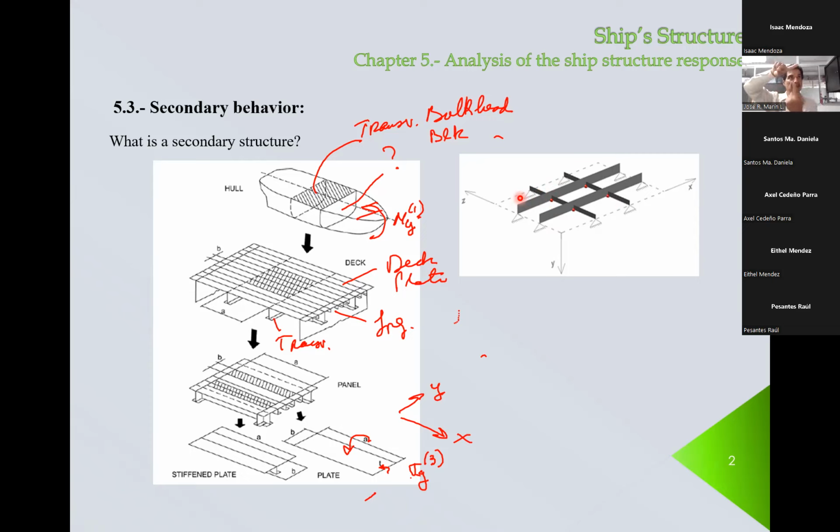So on the stiffener, the force will be upward. And the same force will be acting on the girder, but in the opposite direction. So that's a common quantity. And another common quantity is the deflection, right? The two, because of the load, will deform like that. So the deflection of this and the deflection of that will be the same.